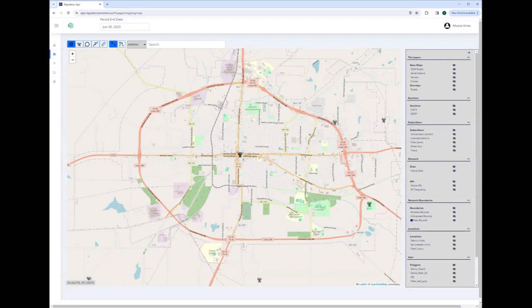So we actually have a clutter loss model. And so we determine each category of clutter that your path might be going through. We determine the total distance along that path for that clutter. And then we apply a loss model. So that's an amount of dB per some unit of distance through that clutter. So it's a little bit more accurate in our opinion.